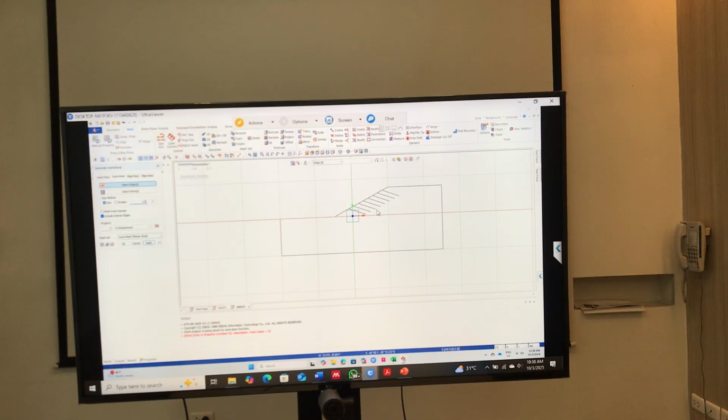Now I just select embankment. This one I unselect. I just select the whole of it like this. I'm also going to take the nails there because they are also embedded in the soil. So I have given it 1.5. I click apply. One more thing, sorry. We need to check the high order. High order is very important.